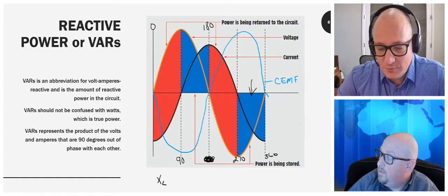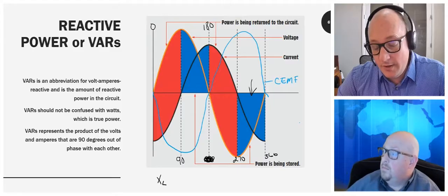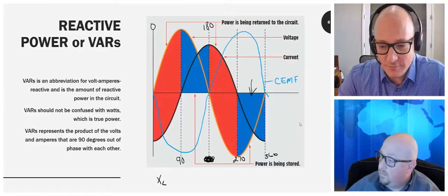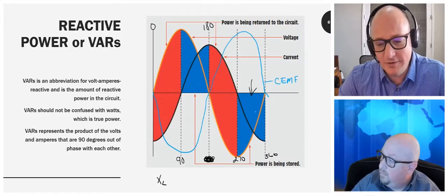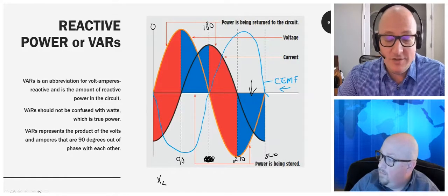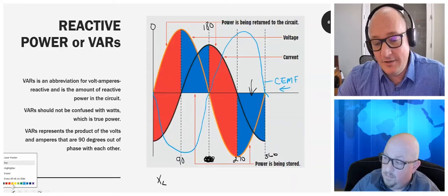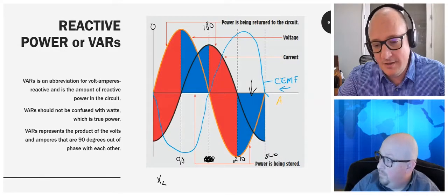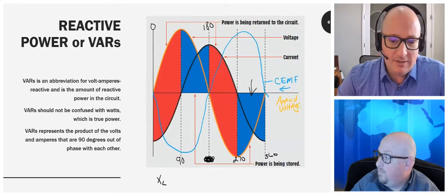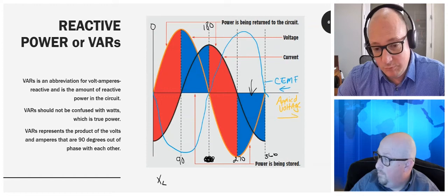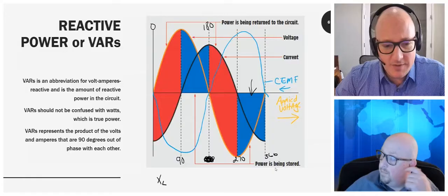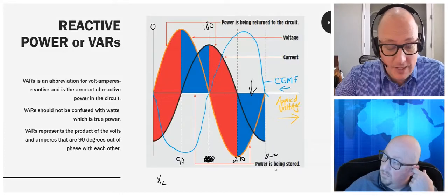You can see that the current is actually at zero. At the peak current point, we've put in the power to create the greatest magnetic field we can. There it is. That's as strong as the magnetic field is going to get, right? And now we change direction. We put all that work in, and the magnetic field we created collapses. As it collapses, it puts up counter electromotive force, there in the blue, and it reaches its peak value when the current collapses at zero.